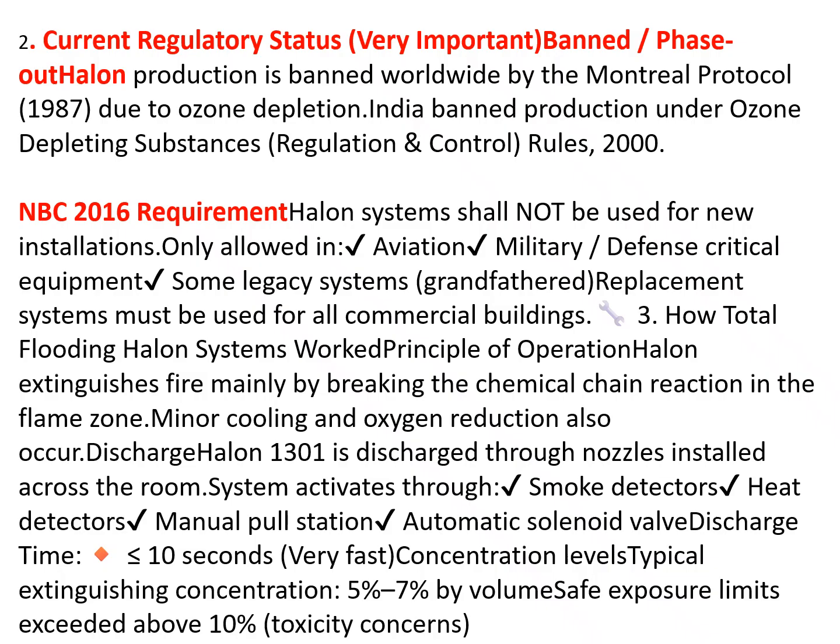India banned introduction under the Ozone Depleting Substances Regulation and Control Rules 2000. NBC 2016 requirement dictates halon systems shall not be used for new installations, only allowed in aviation and military defense, critical equipment and some legacy systems. Grandfathered. Replacement systems must be used for all commercial buildings.